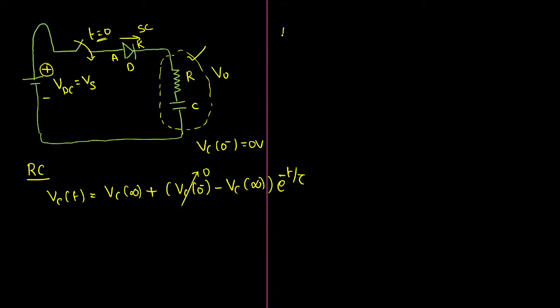Right? Just like we analyzed the inductor, now we do the capacitor at time t equal to infinity. See, the diode will be short circuited and we have only the resistor. At t equal to infinity, what will the behavior of the capacitor be? When a capacitor is permanently connected with a DC supply for a very long time, its behavior will be open circuited. When an inductor is permanently connected with a DC supply for a very long time, its behavior will be short circuited. Okay, so this is the resistor R, and here we have the supply voltage Vs.